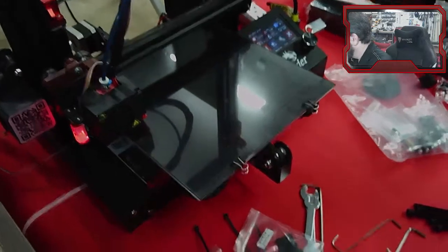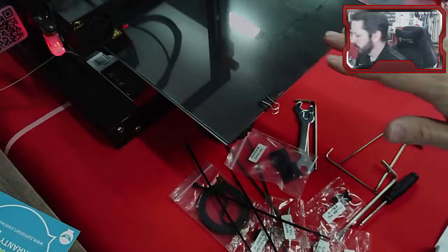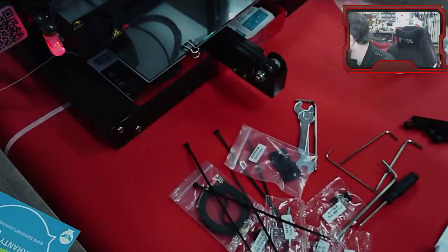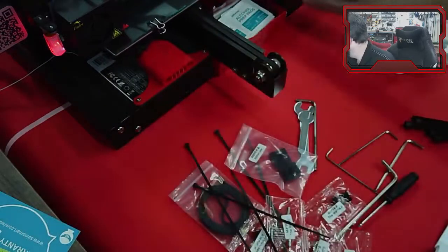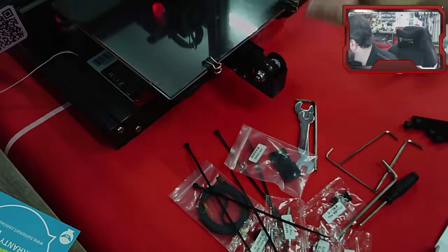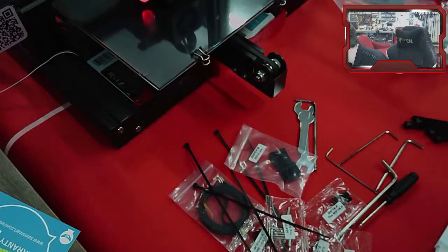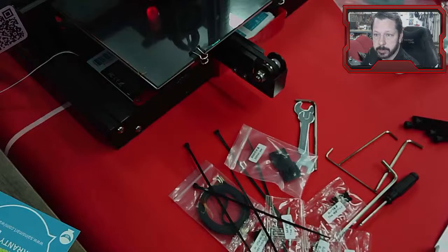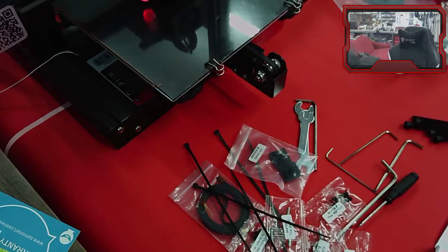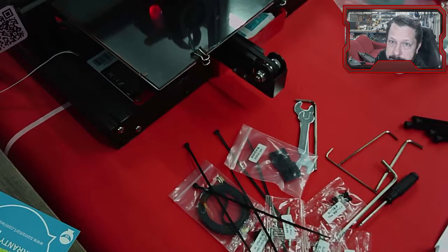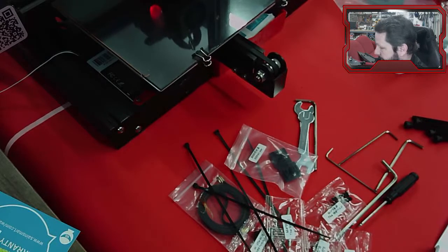All right. Now what I'm going to do here is, last time our part stuck for a while and came loose. So I've got a feature called baby stepping on here, which lets me, as it's printing, lower or raise the nozzle. So I'm going to lower it 1/10 of a millimeter so that it'll print 1/10 of a millimeter closer to the bed, which should squish the filament down against the bed stronger and hopefully make it stick better.